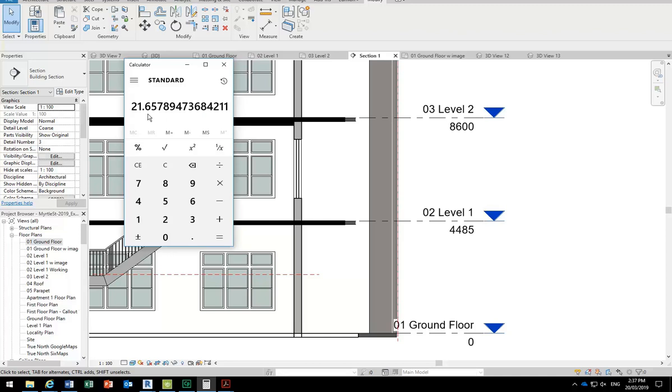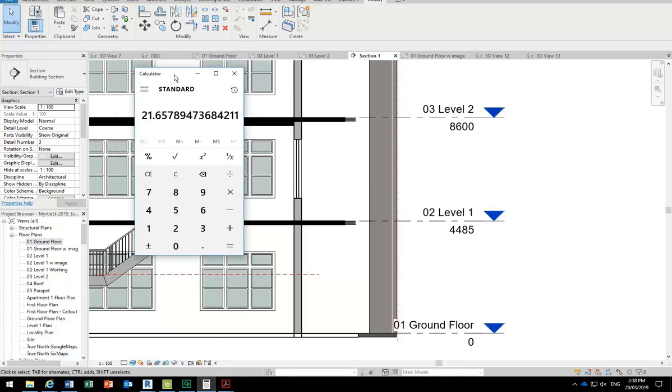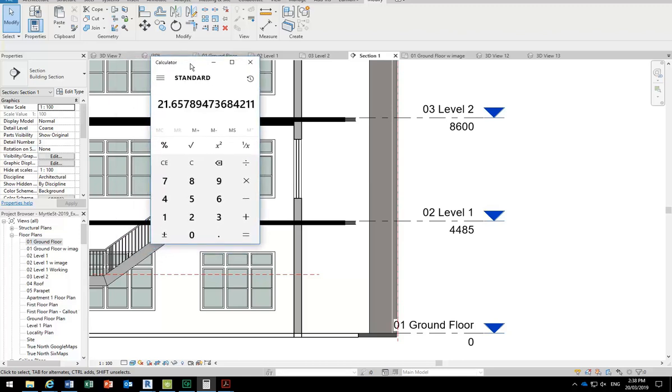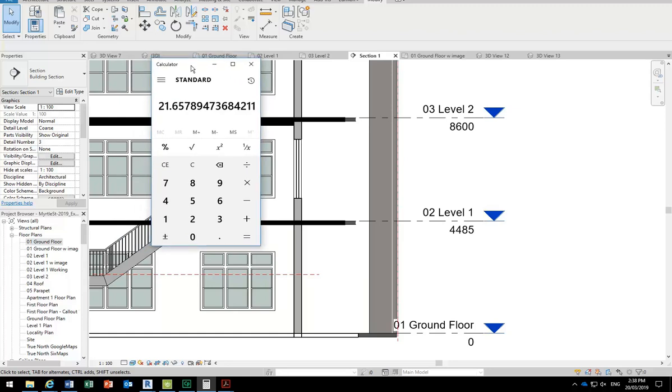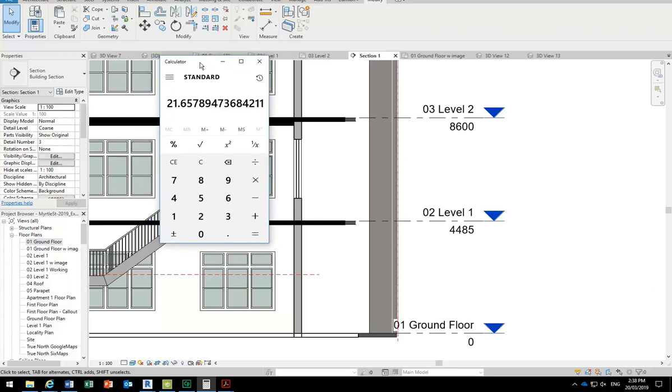So how many rises do we need? Minimum? 22. Right, so always round it up. And I never know how far to go with maths these days because I know you don't have to do maths in the last couple of years of high school. Did all of you do maths in school? Yeah. Good. So hopefully this isn't too difficult, but I'm always surprised when people sometimes tell me that they can't do calculations like this.